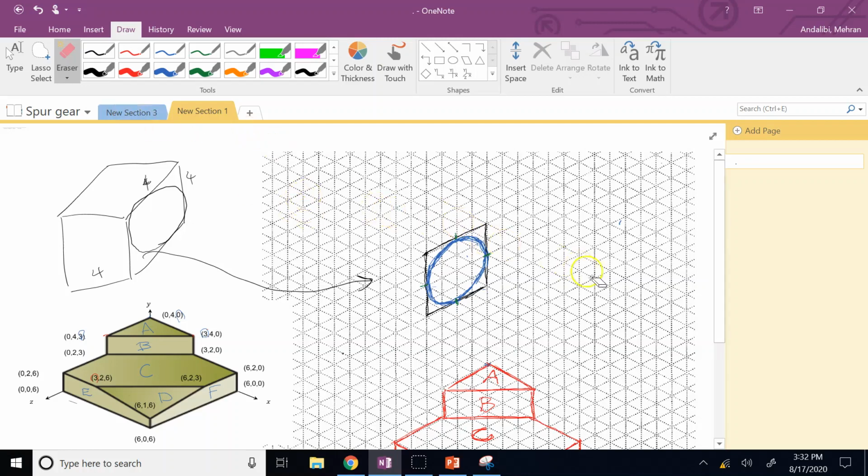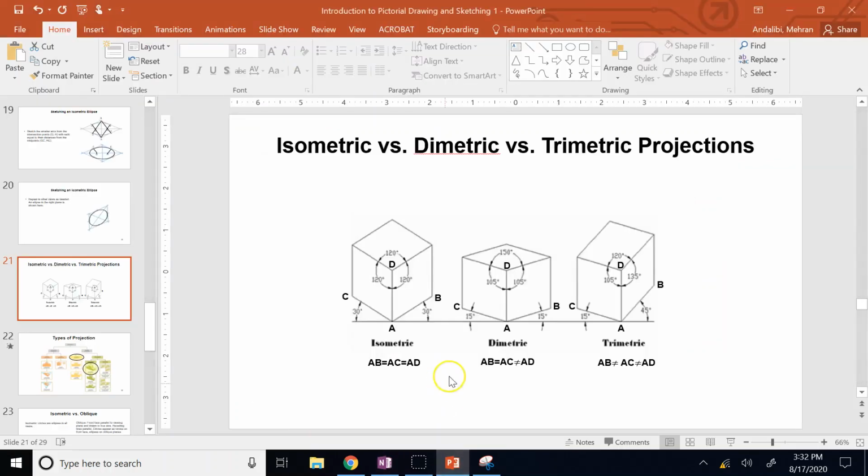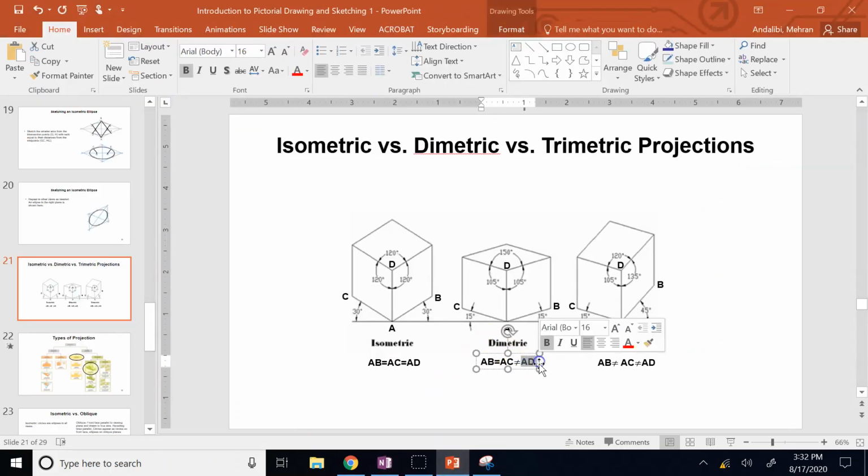The problem is then probably your width or depth is going to be like 4 units, 5 units, 3 units, or so on, but your height is still like 20 units, 30 units, 60 units. So if you want to show a decent size of the building, so don't make the width and depth super small, then even the size of this paper is not enough, or it's going to be really tall. And in order to avoid that, you might use a smaller scale for the height. So use width and depth of 100 to 1, but for the height, you use 300 to 1. So basically shrink it in the direction of height.